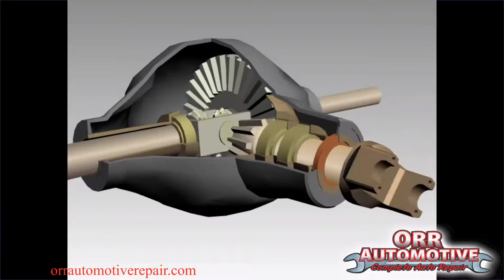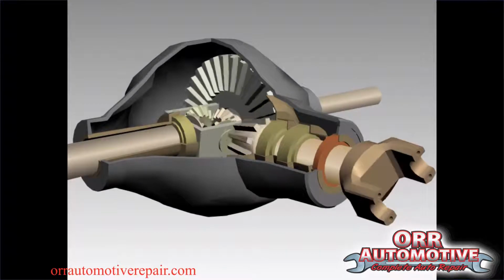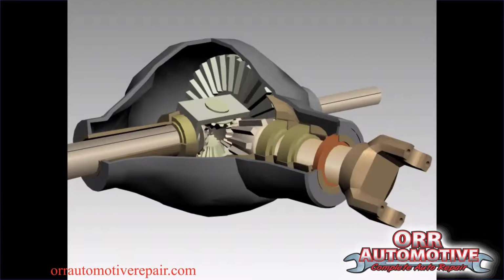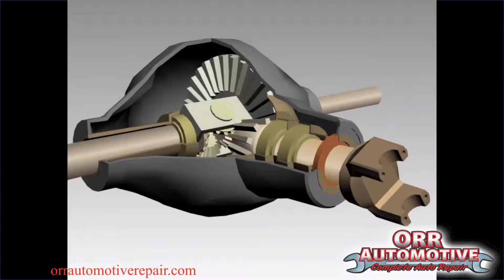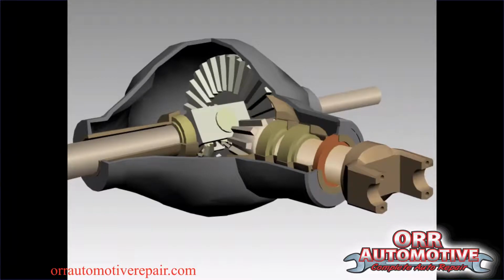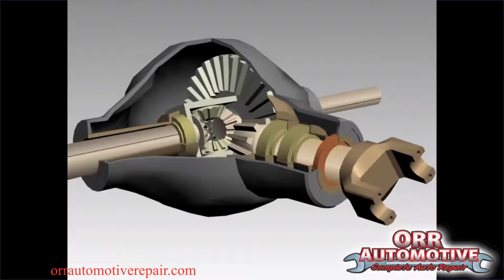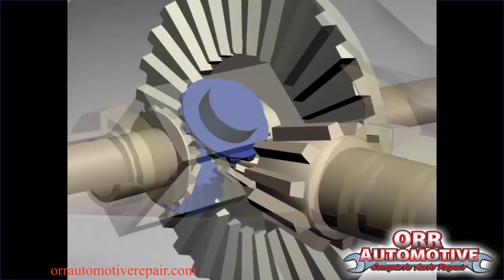When the vehicle is traveling in a straight line, the pinion gear transfers power to the ring gear, which then transfers power to the side gears. When the vehicle is cornering, the wheel on the inside of the corner is traveling a shorter distance and therefore needs to be able to turn slower than the wheel on the outside of the circle. When this happens, the spider gears rotate and allow the side gears to travel at different speeds.